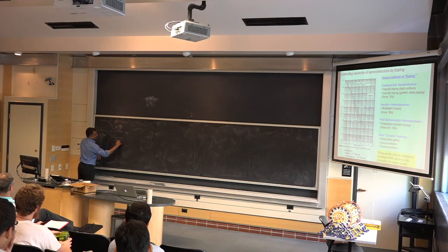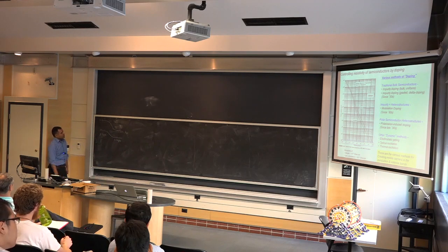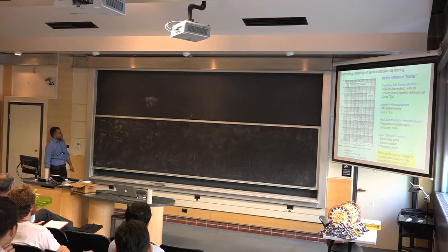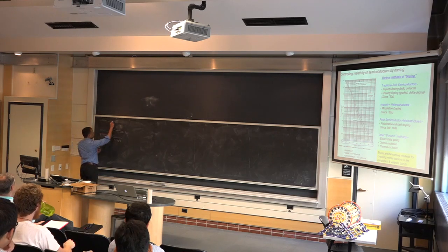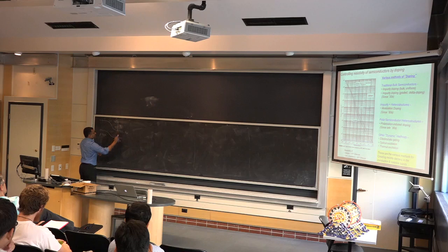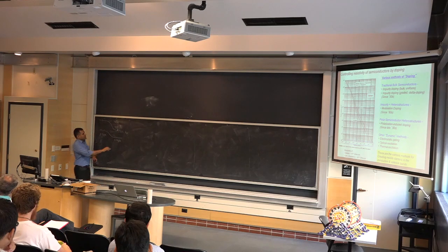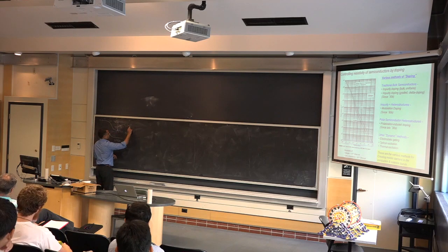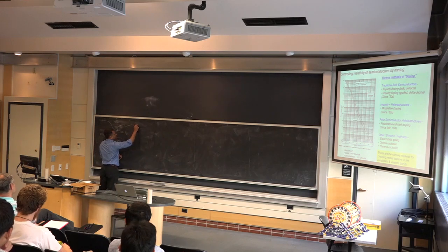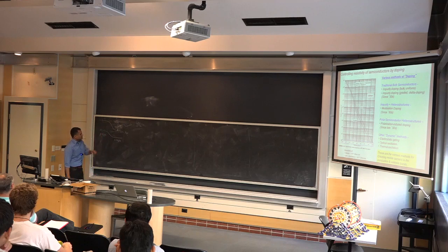We saw that if you put p and n regions next to each other, there's necessarily a bending of the bands. We calculated that band bending, and that's what's called the built-in voltage.